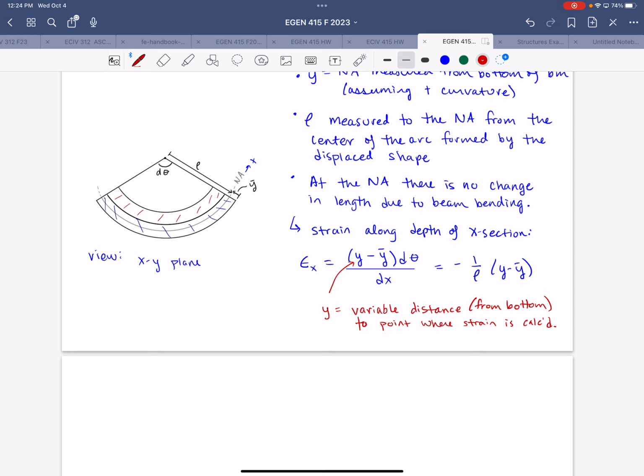So if you were designing a composite beam of some sort, would it be best to try and put the line where they meet at the neutral axis so that you don't have strain going on there? Not necessarily, no. If a goal was to not have any strain or normal stress at that interface, then you certainly could, but usually the bond is stronger than the materials because you don't want that bond to fail. So it's not really that important to do that.